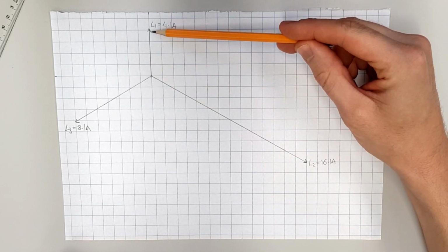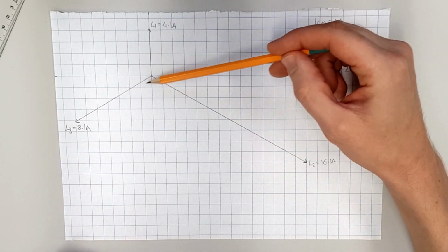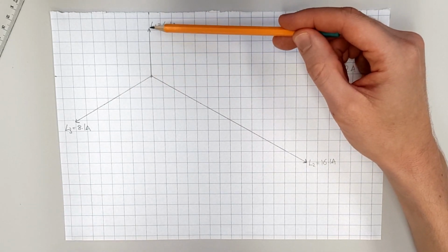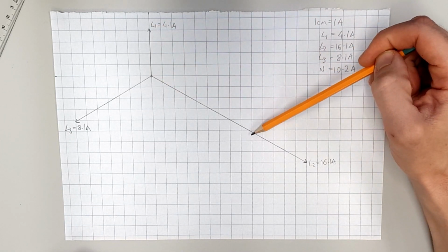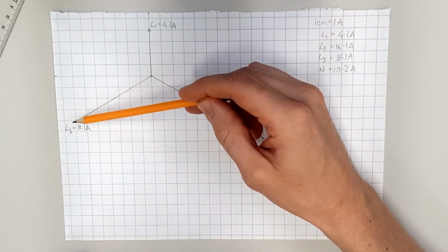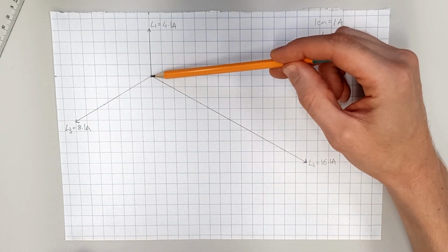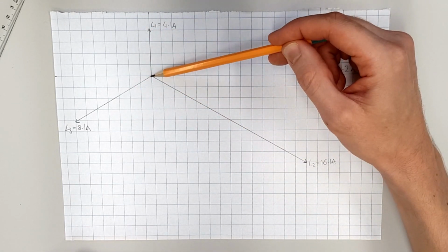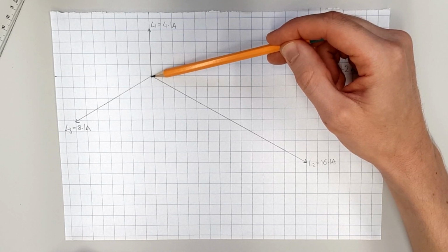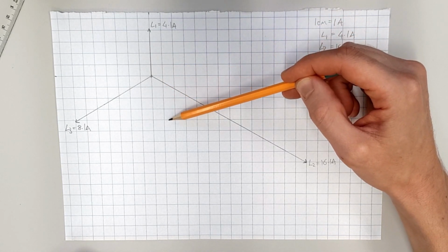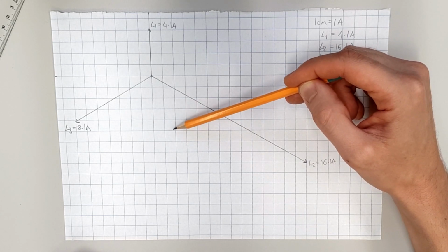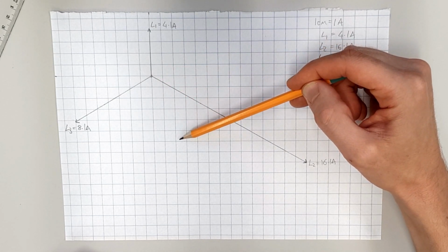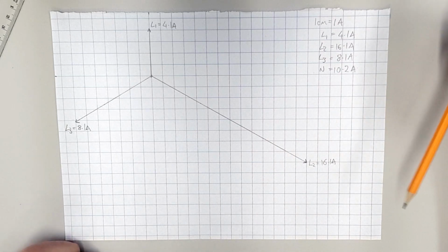Imagine that each of these lines represented a pulling force. So we've got an object in the middle of this drawing here, and it's being pulled in that direction with a force of 4.1 newtons. It's being pulled in this direction with a force of 16.1 newtons, and this direction with 8.1 newtons. What's going to happen to that object? All of those forces are going to kind of resolve themselves, and actually what's probably going to happen is that the object will end up moving slightly off in this direction if they were all pushed on it at the same time. And that's exactly what we're going to figure out, because that distance it would move would represent the value of our neutral current in this analogy.